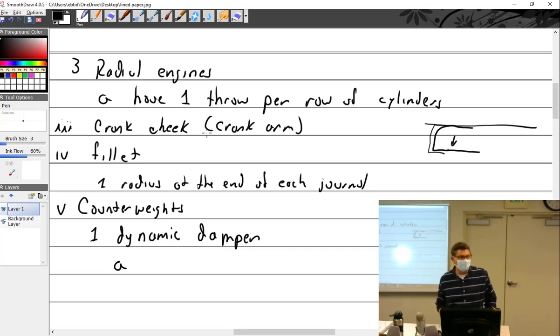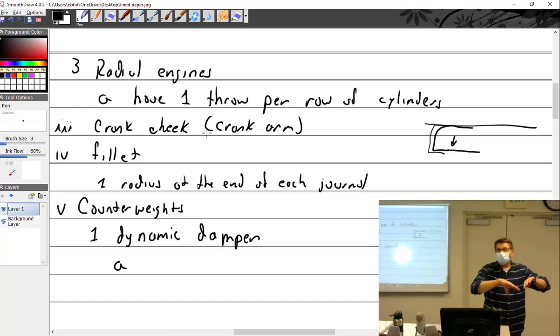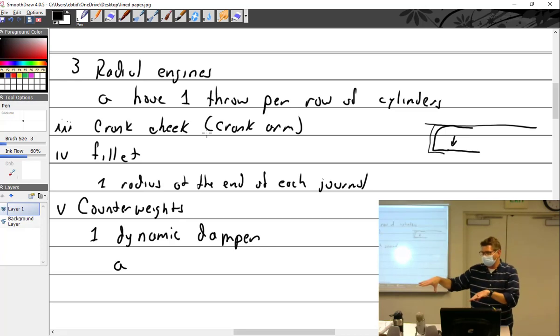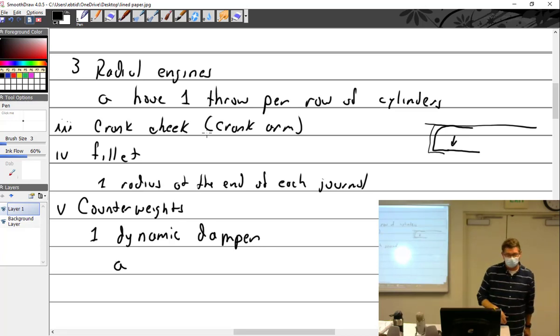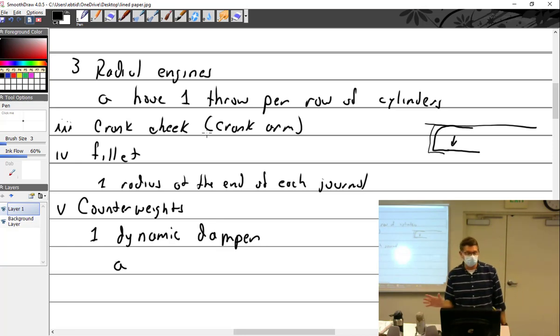I can't do it. So they took the prop off and sent it to a prop shop to have it static mounted. So now you're separating the engine from the prop to see which is the problem. Is it the engine or is it the prop? They sent the prop to a prop balance company. They said, this prop is so far out of balance, so far out of tolerance, you need a new prop. So we got a new prop, put that on, and it hasn't thrown a belt since.